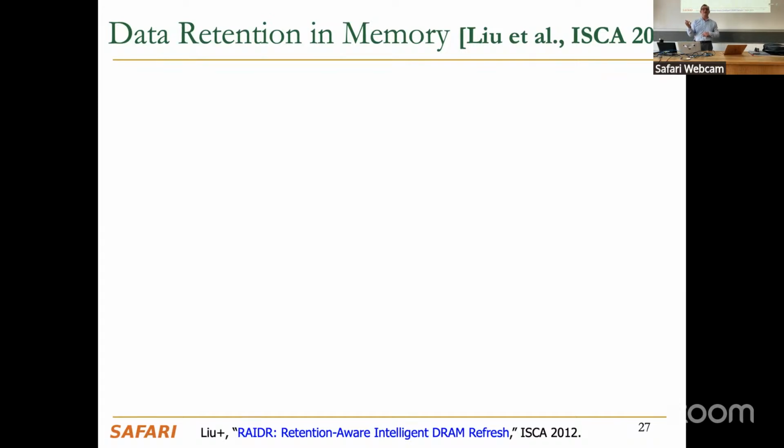One of the main reasons why we built this infrastructure was to see, as you reduce the size of this DRAM cell that I showed you, what happens to data retention capability? Does it become much worse? And how do we actually fix that? Because the cell size reduces, the amount of charge you have in the cell also reduces. And DRAM is dynamic memory. Over time, you lose charge. And you need to refresh memory, meaning you cannot retain data forever. You need to refresh DRAM cells. And as the charge storage unit size reduces, you need to refresh it more frequently, intuitively again.